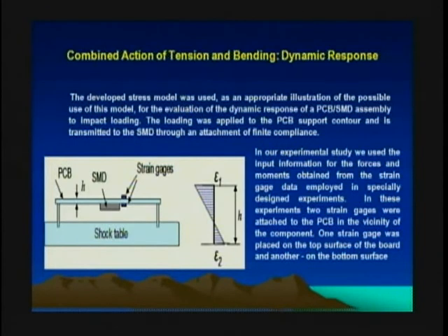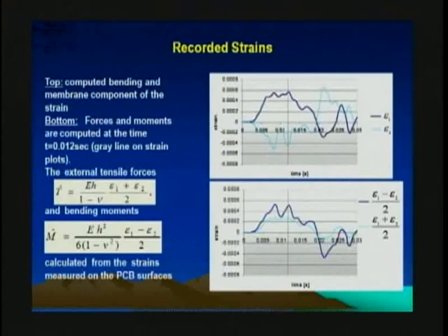on both sides. And certainly, it will be on the next view graph, if you have the reading of these two gauges, you can calculate both the tensile force and the bending moment. Let me show you. And that's what you see with these two formulas.